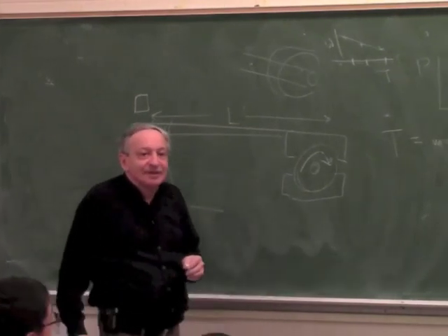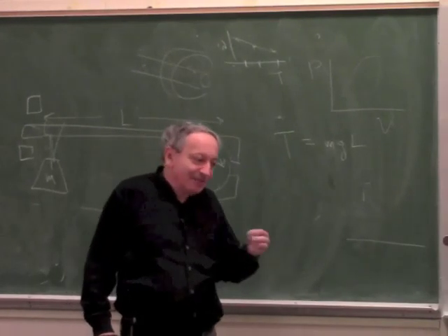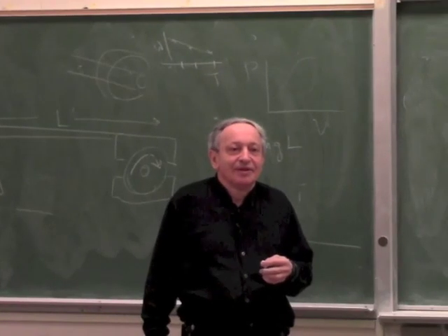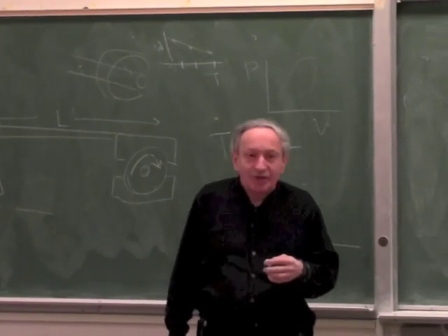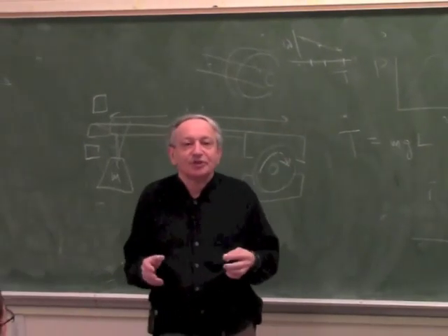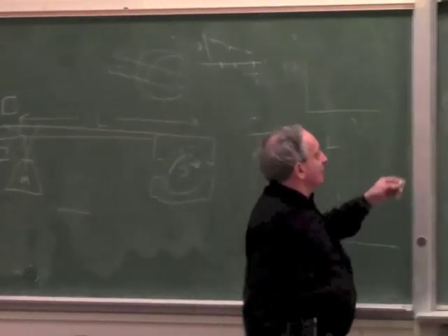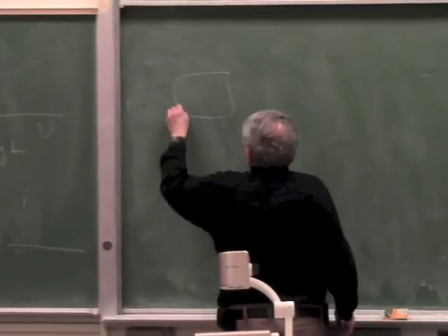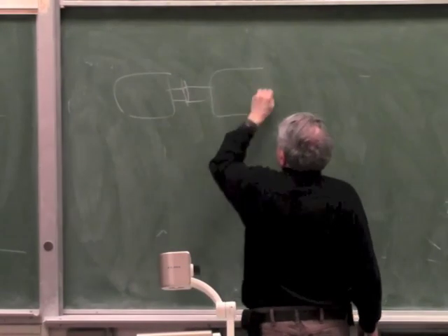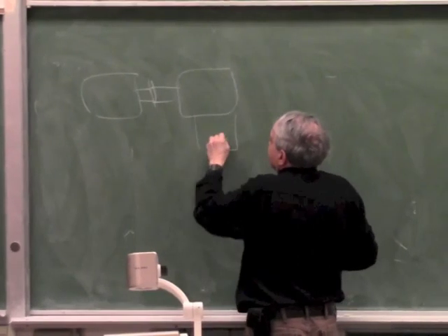Dynamometer? Okay, so what is a dynamometer? Uses water to increase the torque. Okay, correct. So one way to do it is you put a load which is variable. It doesn't have to be water. The load can be a generator. You can take the motor and connect it with a coupling to a calibrated generator. And the generator, you can change the torque by the load resistor.